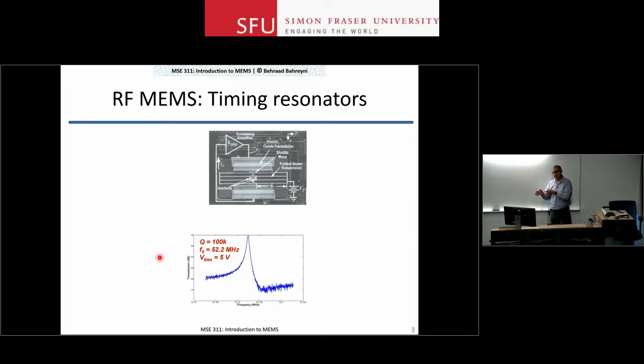You can make those using electrical components, let's say RLCs. The challenge is that in most cases, the sharpness in the frequency domain is not that much. You do not get high quality resonators in the electrical domain. So it has been the case that if you wanted very good resonators, high Q resonators, you had to use a mechanical one.